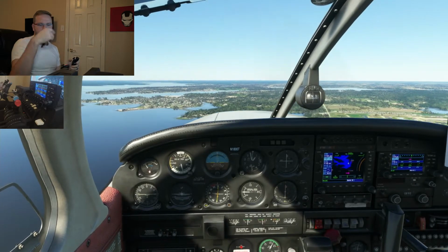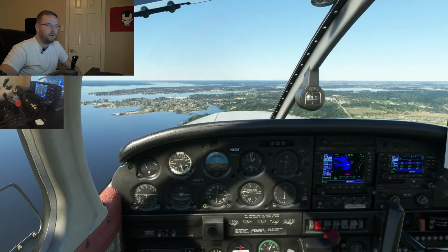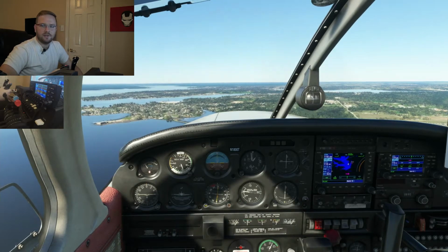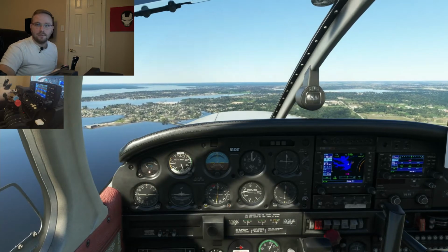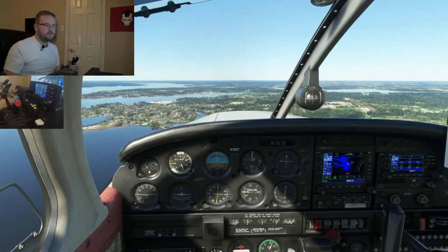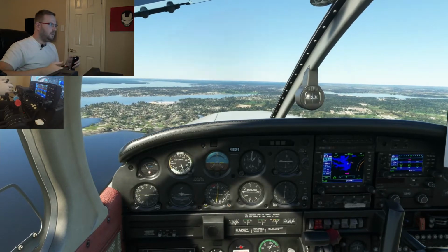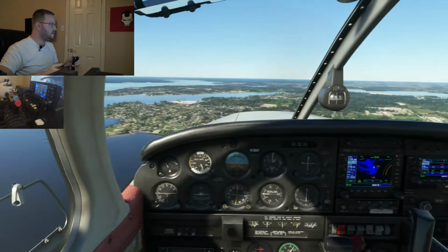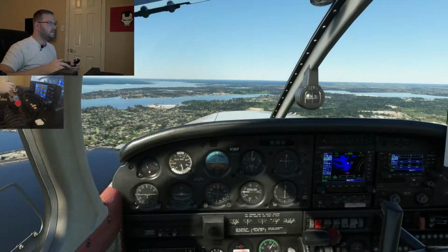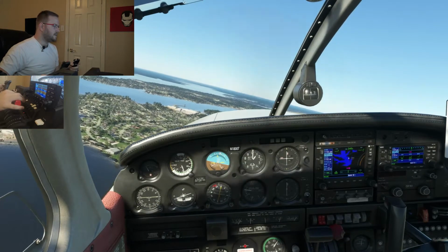Okay. So I'm not going to tune the radio, but we would tune to 123.5. And we would say, Lake Conroe traffic, Cherokee 1800 Tango, doing turns around a point over the island, Lake Conroe traffic. So we're going to maintain 1,000 here. And is it behind us more or less yet? Yeah, okay. We can go ahead and do our clearing turn. So we're looking for airplanes, want to maintain 1,000.